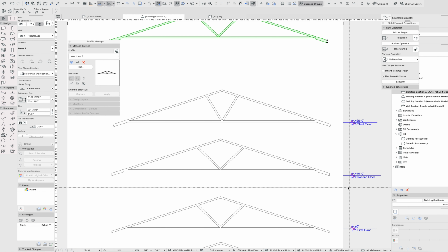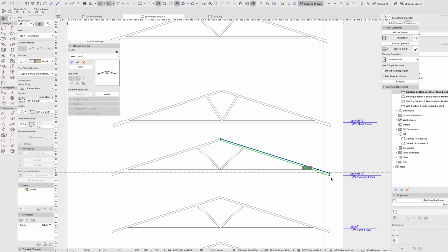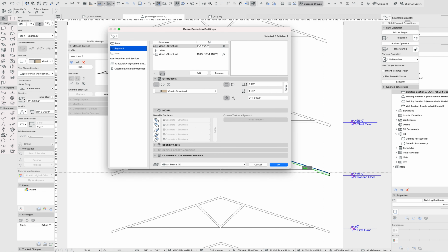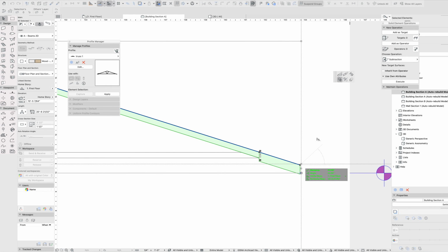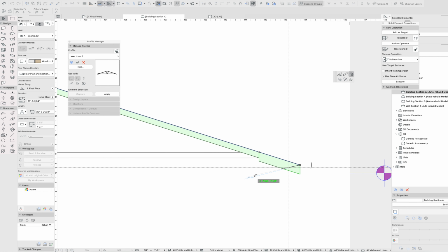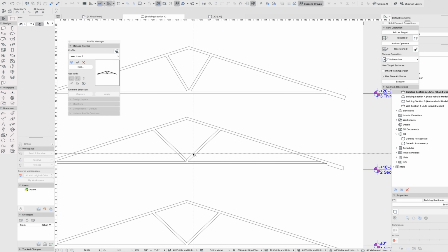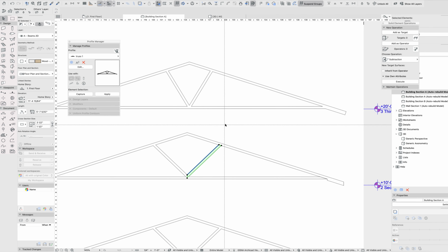It works really well. You also have the option, because they're beams, to include segments, so your rafter tails can actually be different. You can even edit them sort of on the fly. If you're using the live beams, you can use the pet palette and start playing around with some of these cuts, these thicknesses, the connections between them. Adding a new strut in like we did down here is pretty simple. You can just literally mirror it across an axis, mirror copy.